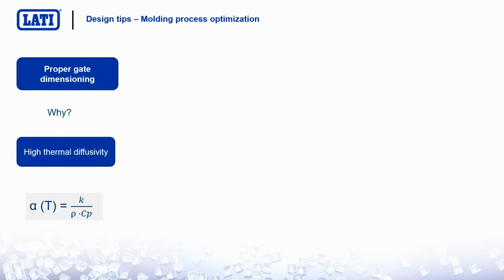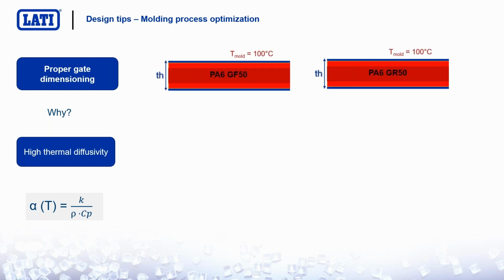Why? Because due to the high thermal diffusivity and thermal conductivity of these compounds, we have at our disposal a much shorter time to properly inject and pack the molded parts, before the gate freezes.